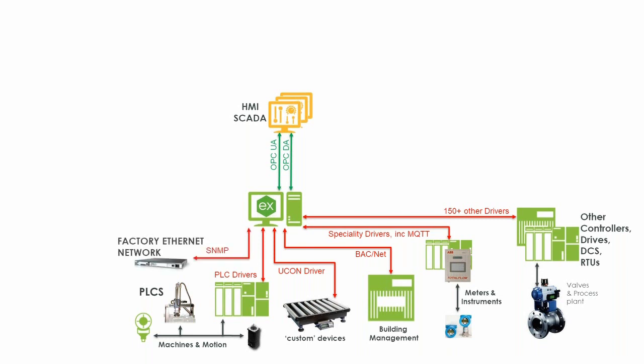A lot of you watching today will have Ethernet on the shop floor, and those devices will be talking SNMP. If you send them Simple Network Management Protocol packets, they will respond with their status. And SNMP is a very well-known, very widely used protocol for monitoring IT systems in an IT environment, but Kepware have an SNMP driver for monitoring industrial type Ethernet devices in an industrial environment.